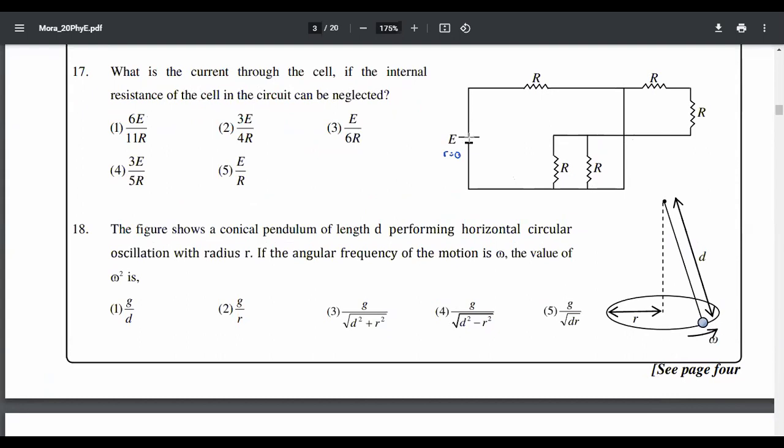See, now I'll mark it in blue color, the path of the current flow. It can go here, current can go up to here, then current will go here, and current can avoid both the resistors and go this way, right? Current doesn't have to go here. Why? There is a short circuit. Again, current can avoid these two resistors and go this way.